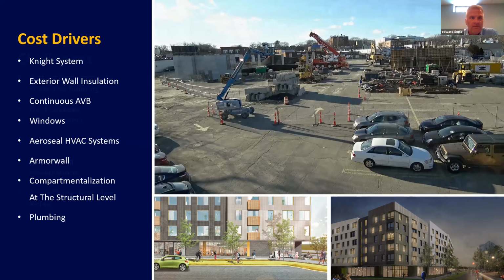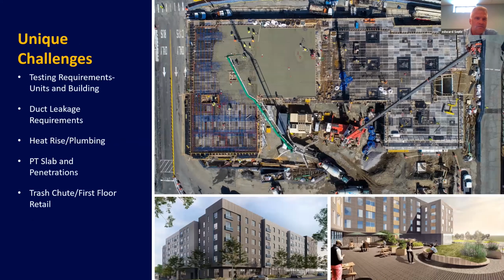That's some of the cost drivers. Unique challenges for us: testing requirements, previously talked about. Multiple mock-ups, highly recommended. Blower door tests, we're going to do them by floor, by wing, before the facade's put on. Everything that the previous presentation talked about is a big deal.